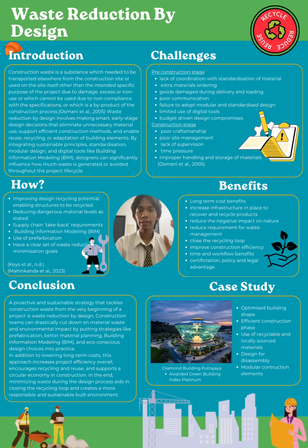Other than that, designers used recyclable and locally sourced materials, lowering transportation emissions and promoting regional economies. The building was designed for disassembly, which allowed materials to be reused at the end of its life. It also adopted modular construction elements, improving build speed and reducing errors. This building proved that sustainable design is not only possible, but also practical and efficient.